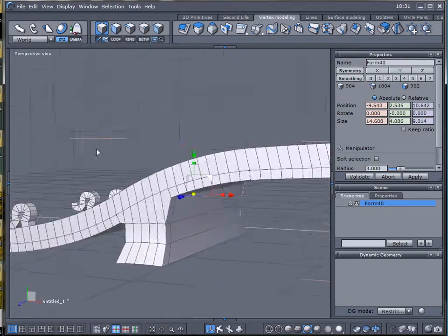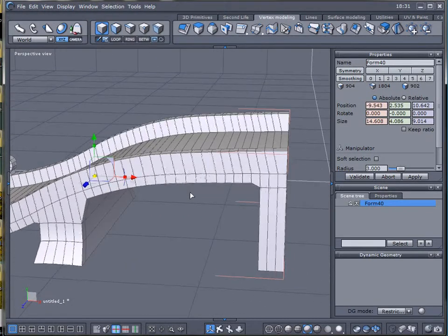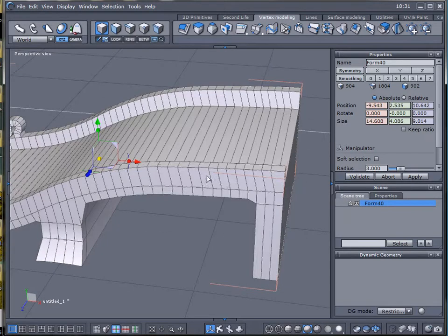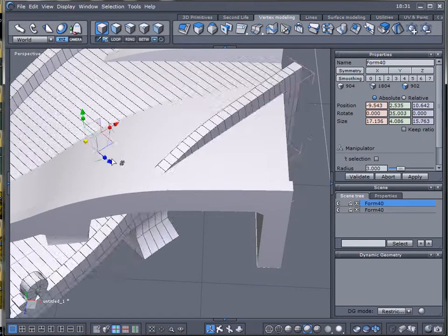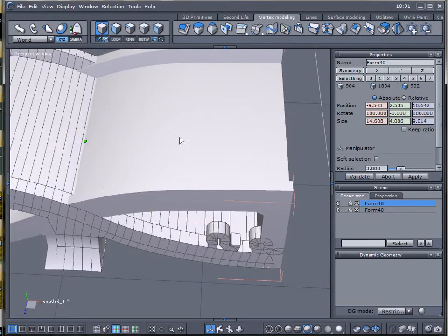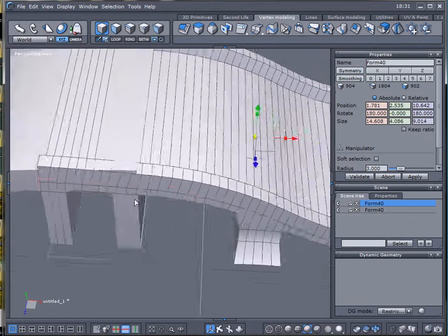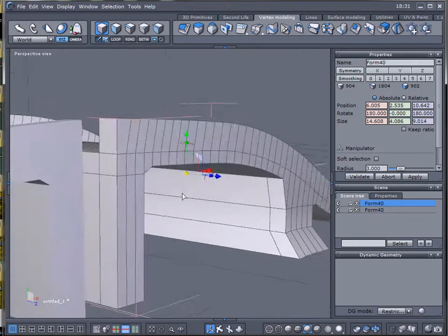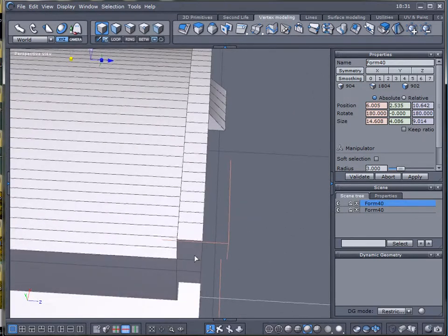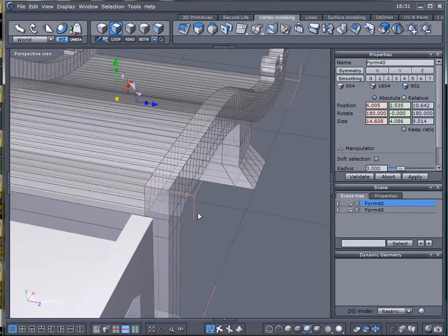So we say we're done, for example, with this side, and I want to create the opposite, so we'll select the bridge. Press Control D to duplicate it, go to the rotation tool, and start rotating. Hold down Shift so it will lock. Move a little bit to the end, and now we want to merge them together. But before I do this, I want to select and remove these faces. Just select and click delete on the faces.